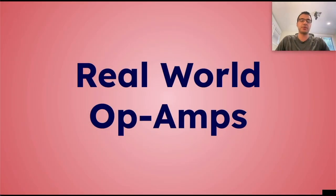Then we'll move on to real-world op-amps, and this is a separate total section where we're going to talk about all of the non-idealities of real-world op-amps, how to choose them for a specific application. You know, the fact that they don't have infinite input resistance, infinite output resistance, etc. So we'll take a look at all the non-idealities, their common mode rejection ratios, their gain bandwidth products, their stability issues, and on and on.